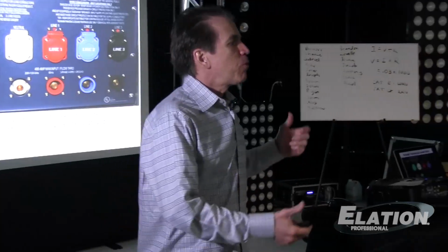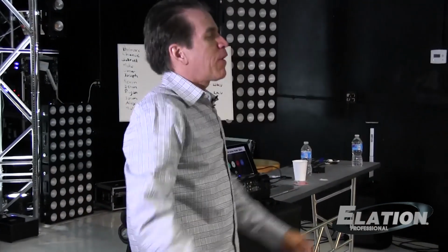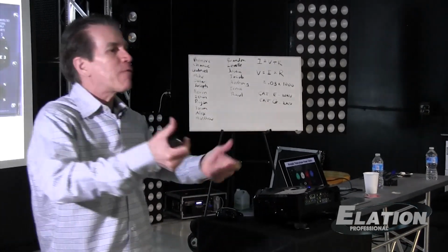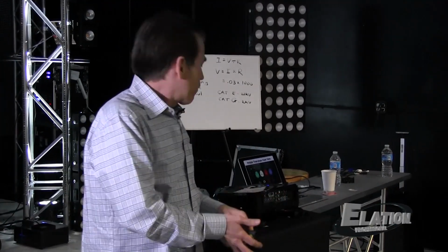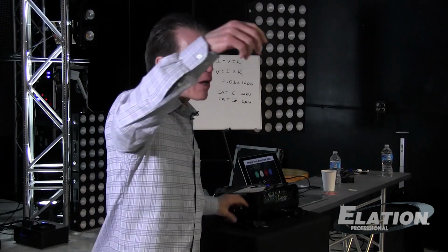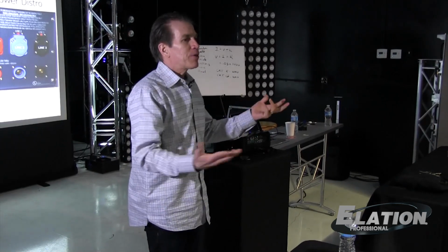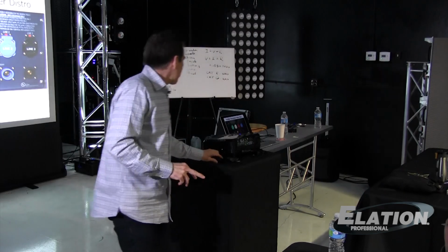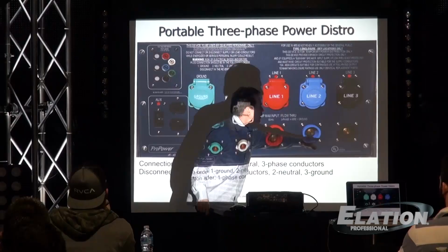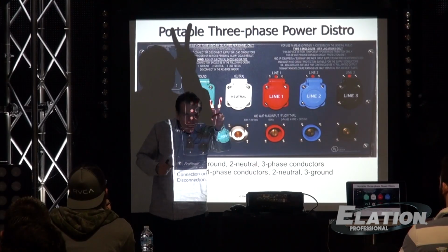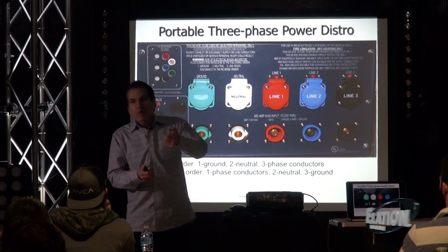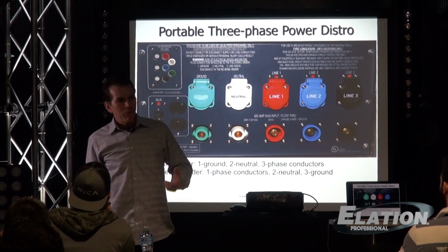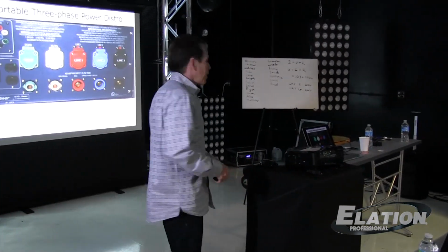And if you are flying hoists or flying truss, and you have your pickle for the motor control, you've got your chain hoist connected to the truss. If you press the up button and the truss goes down, what do you do? Reverse any two phases. That means you can come to any of these three connectors and swap two of them. Now when you press the up button, the truss will go up, and when you press the down button, the truss will go down. So you swap any two phases.